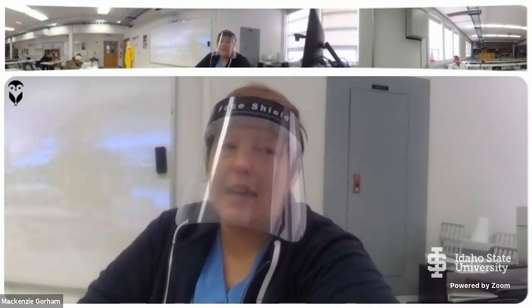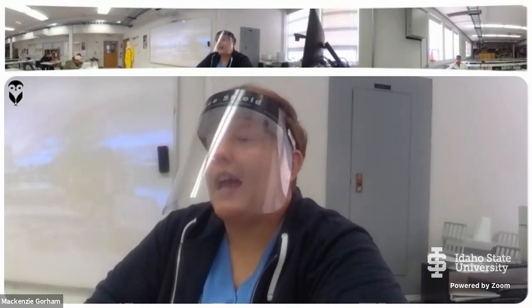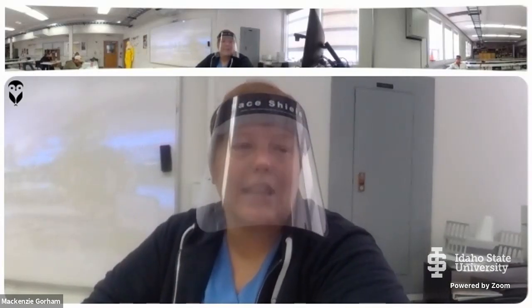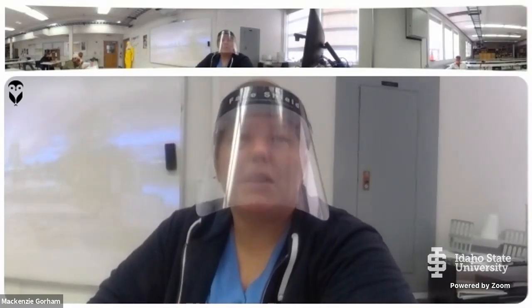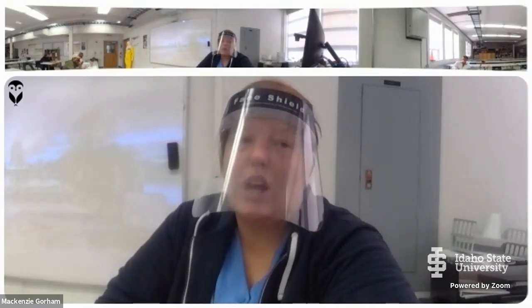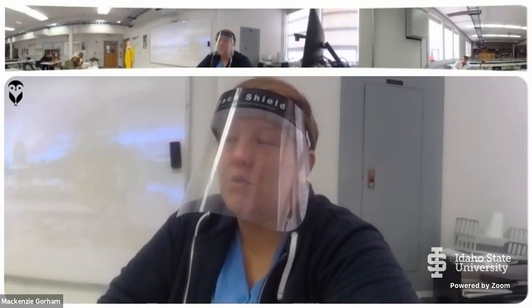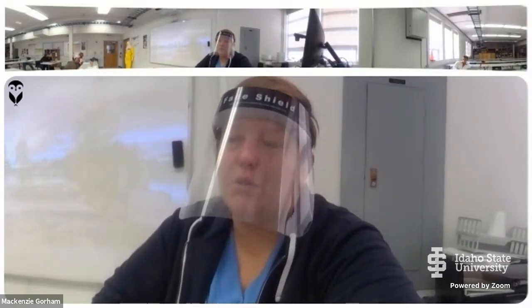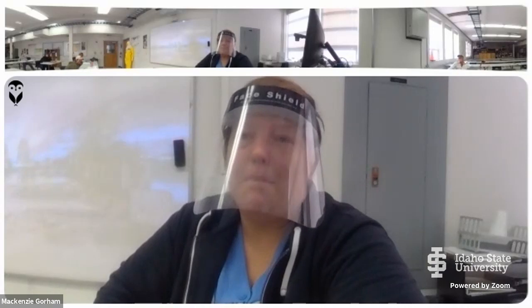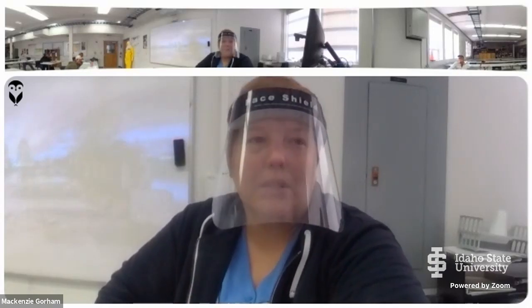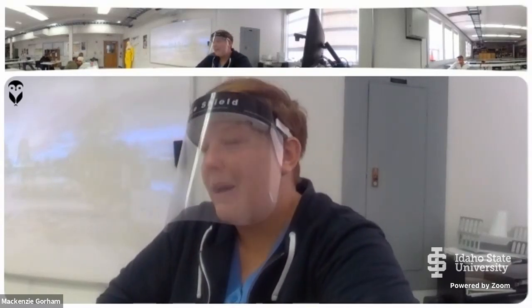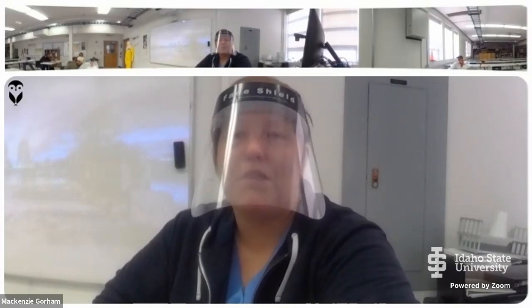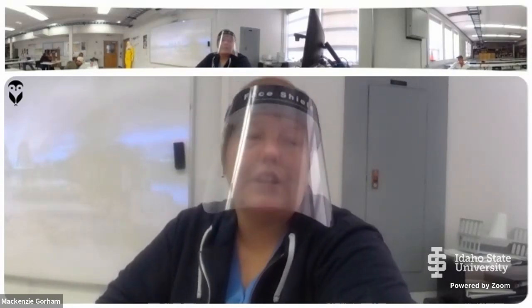And that chaining together of work to stay under dose is not as efficient as letting somebody finish a task if it's safe to do so. So work control wise, it's also desirable that on some of the jobs where, hey, this one job is going to take this few amount of hours for you to do, you're going to get your whole year's limit and you're not going to go into a radiation area the rest of the year. That might be the safest way to do that job rather than trying to chain together people doing certain parts of it. And in commercial power plants especially, that is a consideration because some of the outage jobs you have to do have a very high rad dose field that you're working in.